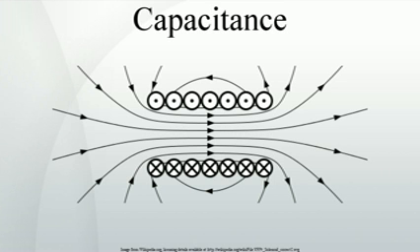When a parallel plate capacitor is filled with a dielectric, the measurement of dielectric properties of the medium is based upon the relation where a single prime denotes the real part and a double prime the imaginary part. Z(ω) is the complex impedance with the dielectric present. C_cmplx(ω) is the so-called complex capacitance with the dielectric present, and C0 is the capacitance without the dielectric.